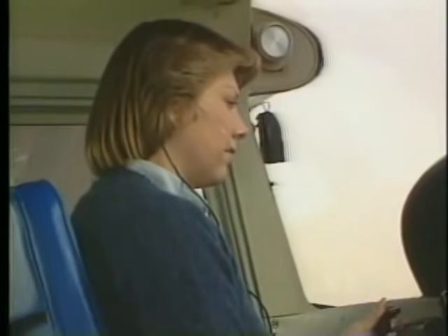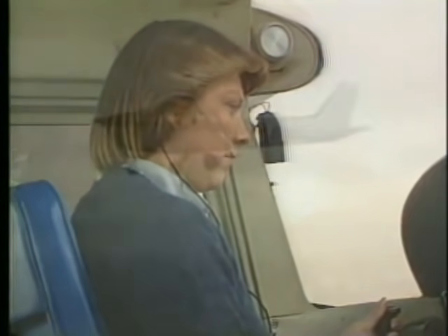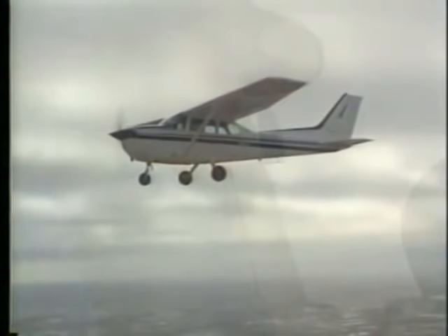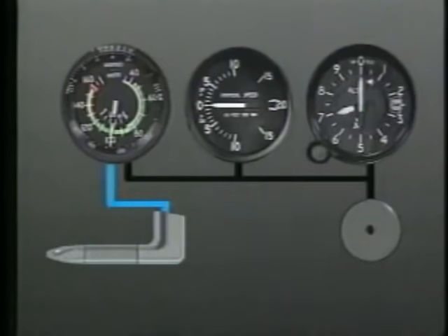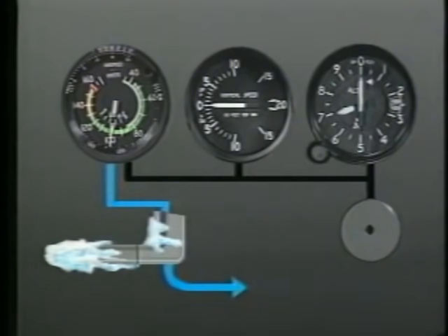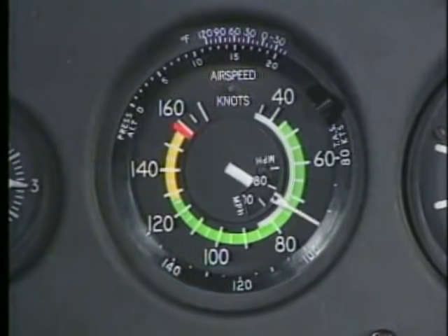As an instrument pilot, you should be aware of the erroneous readings which can occur if the pitot-static system becomes blocked by ice, dirt, or even insects. If the pitot tube becomes blocked, two types of errors can occur with the airspeed indicator. If the air inlet is blocked but not the drain hole, the pressure in the line will vent out the opening, causing the indicator to drop to zero.